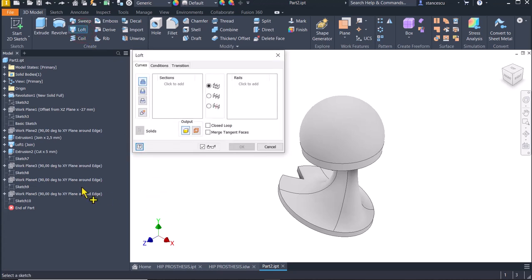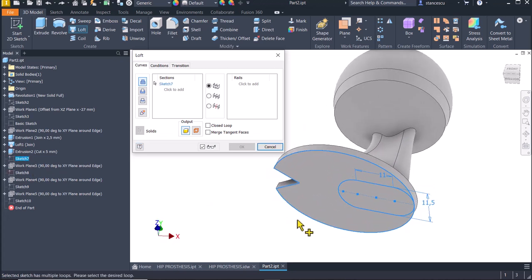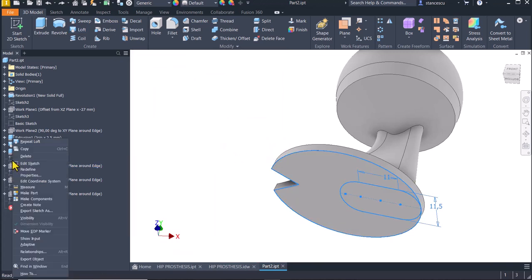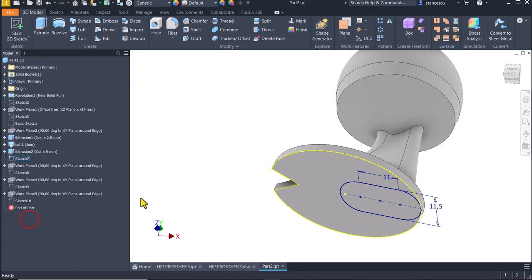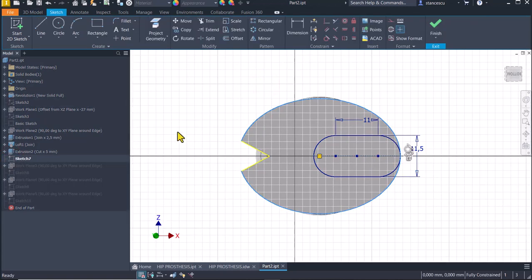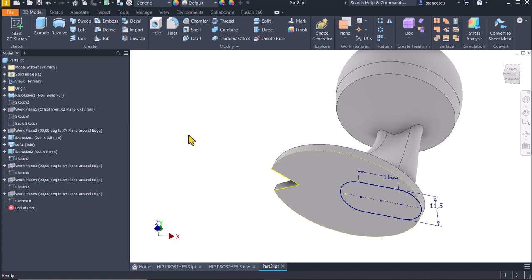with this face, but you see we have two closed contours. We have to edit this to eliminate at least one component of this external contour. We apply visibility, double click on it, and this is sufficient to be construction. Now we don't have two closed contours.